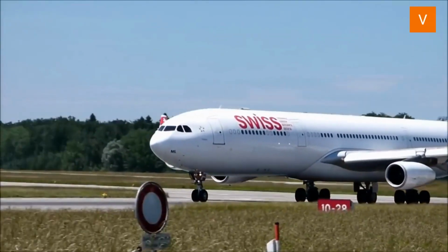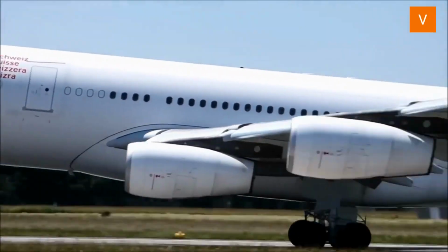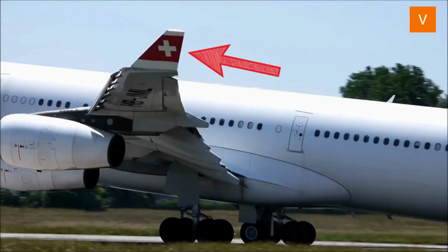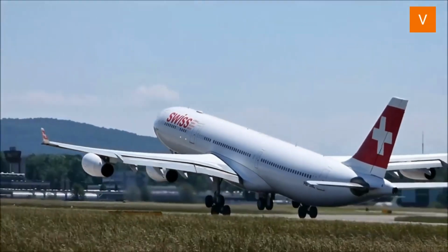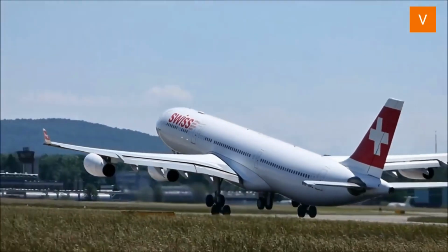Winglets are used today to increase an aircraft's aerodynamic abilities while flying. When an aircraft is in motion, tip vortices form at the ends of its wings. This is from the rotational motion of the air flowing off the wing, causing drag on the aircraft. Winglets reduce drag on an aircraft by forming smaller, more disoriented tip vortices.